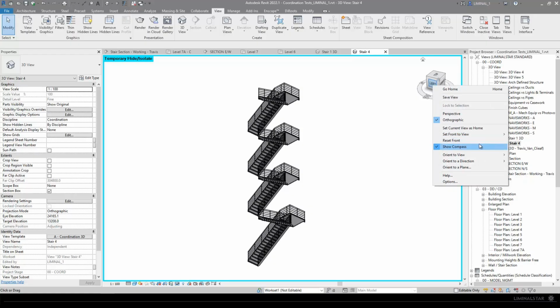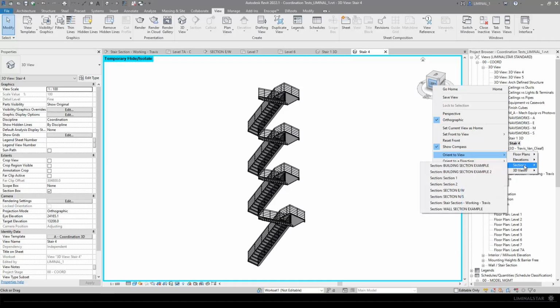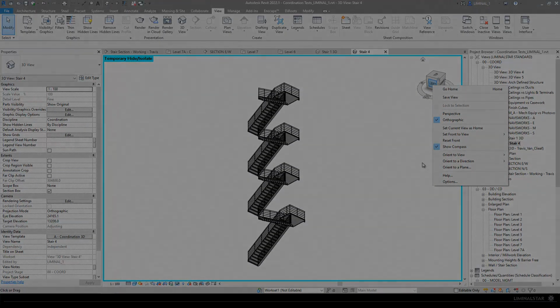And you just want to remember to always change the name of your view, because whenever you click back to the default 3D view, it's always going to go back to what your username is, which is super handy. But this oriented view gives you the option to do this with floor plans, elevations, but I think it's really powerful with sections and floor plans to show visual context of what's happening on the inside and outside of a building at the same time. So anyway, that's a little bit of navigation and keeping in a flow state while you're trying to navigate through your model, and leveraging what you know of your view types, your view templates, and your browser organization to kind of bring that all together for a nice smooth experience.